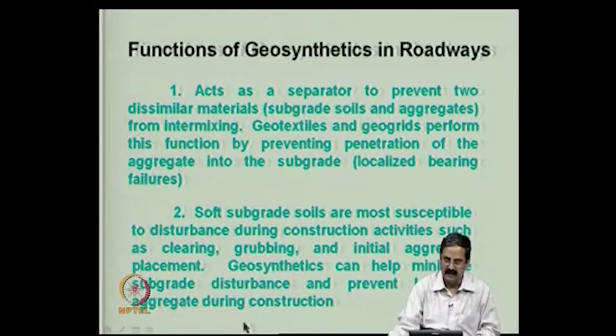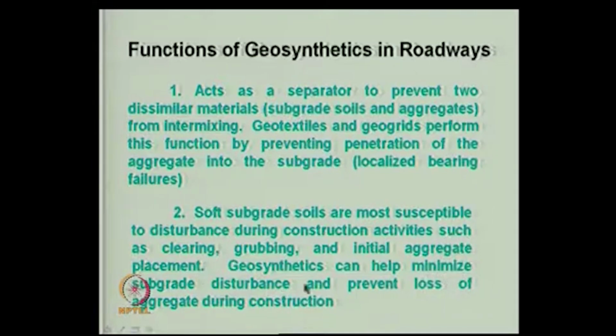The second thing would be that soft subgrade soils are very susceptible to disturbance during construction activities such as clearing, grubbing and initial aggregate placement. Geosynthetics help in minimizing subgrade disturbance and prevent loss of aggregate during construction.